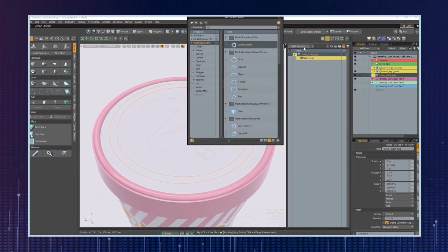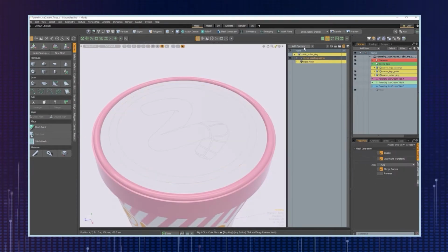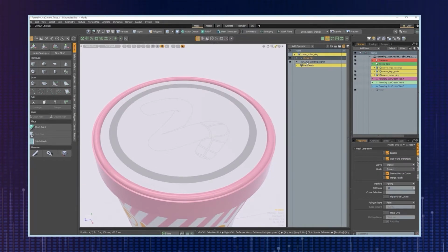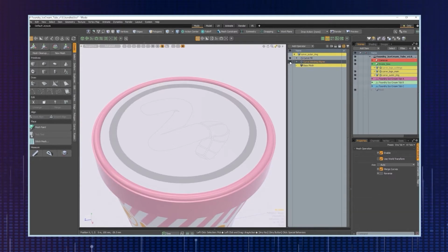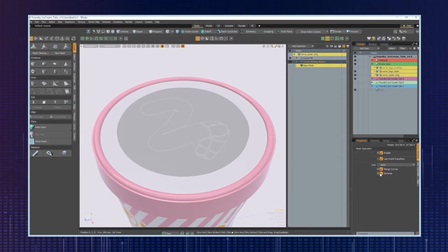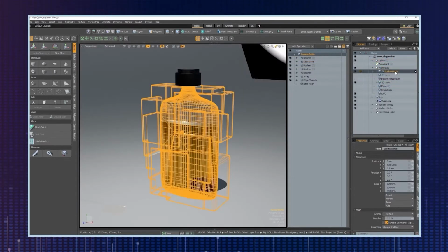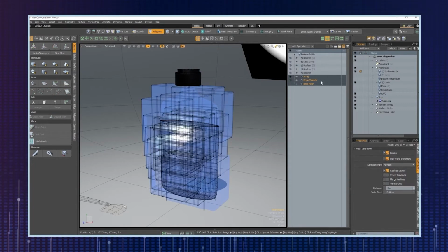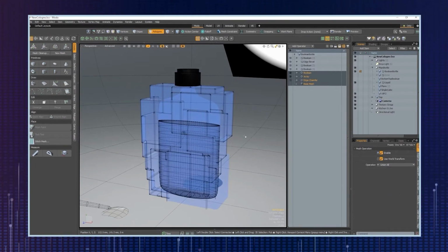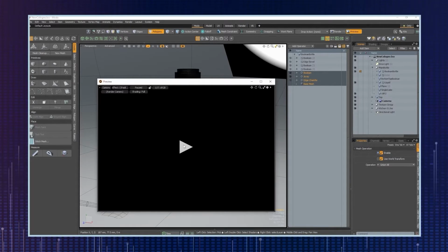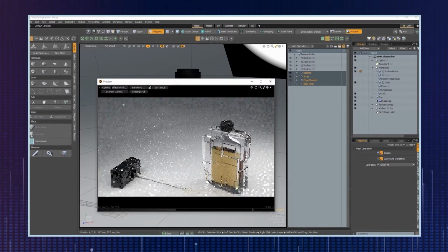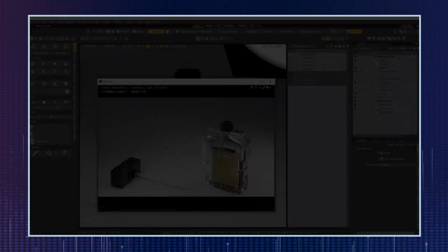With the new workflow comes the need for easier preparation too. So we're also introducing the Curve Winding Aligner procedural operation. This handy tool gives you total control over a curve's winding direction, so setting up your curves for later operations is more straightforward than ever. And our Boolean CSG operation has a new mode, Union All. This mode unites all the polygon groups in an active item layer without the need for a driver mesh item. When you select multiple item layers, the union result will be applied to the primary active mesh.